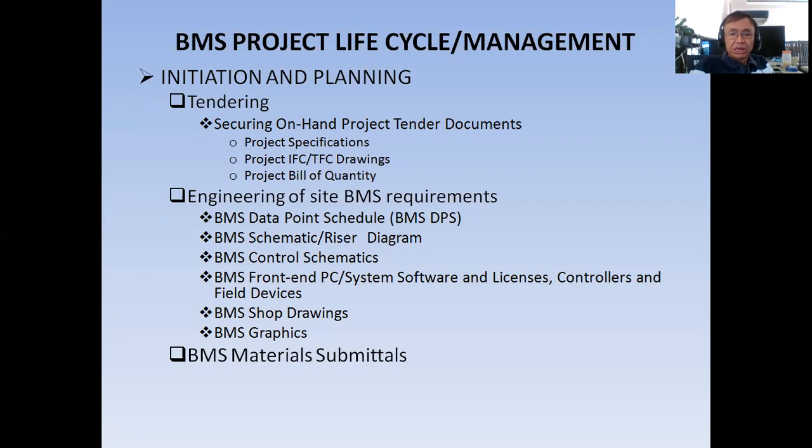And finally, the field devices. You have to finalize all the field devices that you're going to use for the control and monitoring of different equipment. Then BMS shop drawings. The BMS shop drawing will show the connections of an equipment to a DDC panel, the field devices connection to the DDC panel.